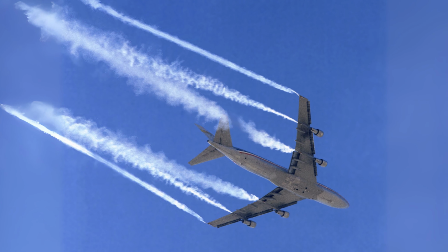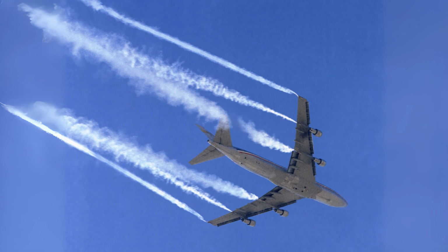But if you fly closer behind an aircraft, you'll be flying into a vortex that's still fairly well developed. This swirling air can induce a roll if it's strong enough. The intensity of the rolling effect experienced depends on the preceding aircraft's wingspan and the strength of the vortex. When the aircraft encounters a vortex and it's strong enough to induce roll, the pilot counters it by using the ailerons against the roll and tries to fly out of the wake as soon as possible.